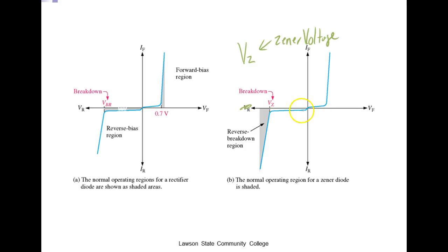So if we protect it, I come over here and put a resistor right here, then a Zener right here, and connect this to common. I'm going to put a plus voltage right there, because that would reverse bias it, right? Then we get up to a certain voltage, this thing's going to break over, and it's going to maintain a fairly constant output. If I put my load right there, it's in parallel with the Zener. So whatever the voltage drop across the Zener is, that's going to be the voltage drop across the load. Pretty neat.